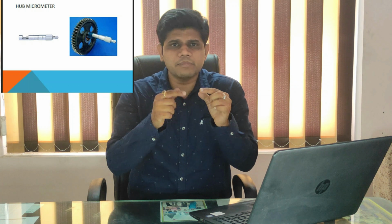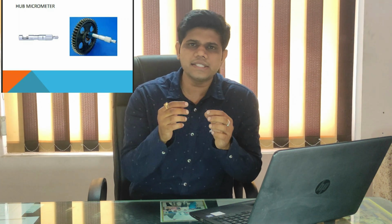Hub micrometer. As you can see in the display, it is a very shallow type of micrometer. Generally we have to go inside shallow or small diameters and measure the wall thickness of that part. This hub micrometer helps us measure that area, and you will get an exact result from a very small hole. It is also used as a wire micrometer, where small wire diameters are measured, and you get a very good result. The hub micrometer is also one of the newest and latest micrometers.